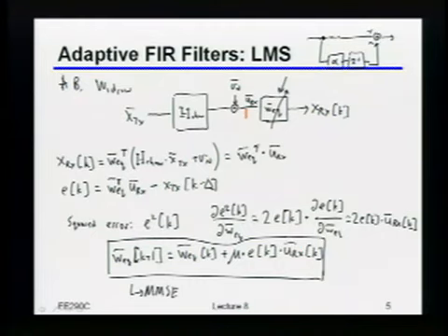Other questions on this? The current error is E of k. And what came into the equalizer, the only trick is that when I called this URX, I'm still saying it's of k here. But remember, there may be a bit shift because of this delta that I've inserted. Does that make sense?